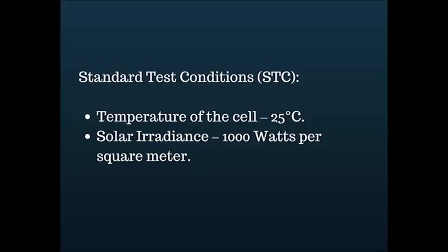Module performance is tested under predetermined conditions. These are the standard test conditions. To meet the test conditions, a cell temperature of 25 degrees Celsius and an irradiance of 1000 watts per square meter must be respected.